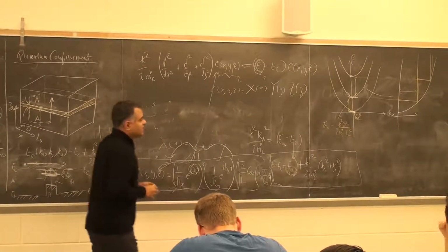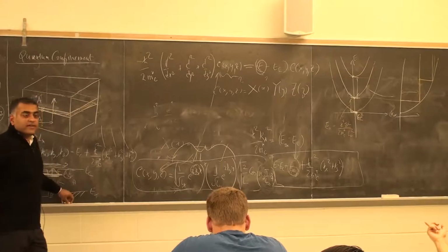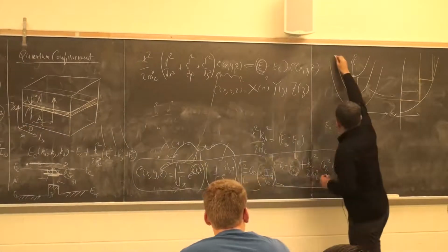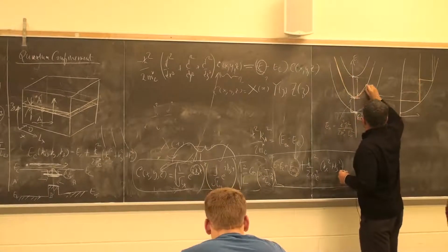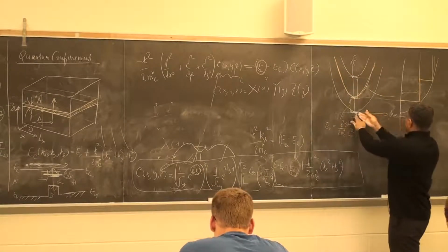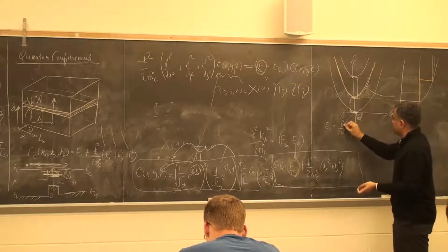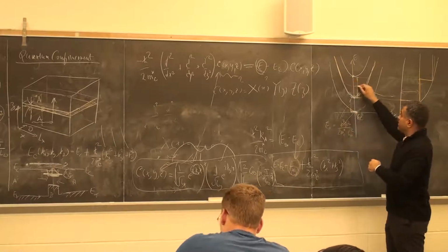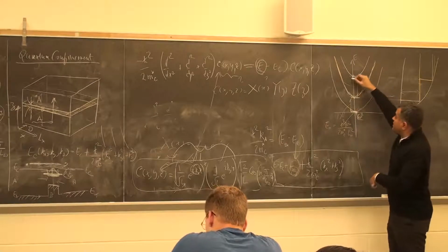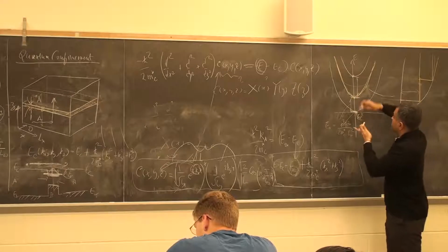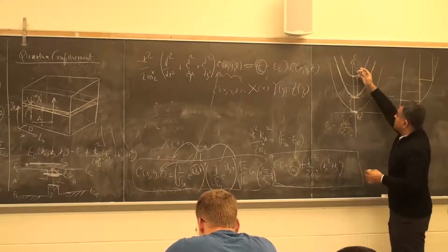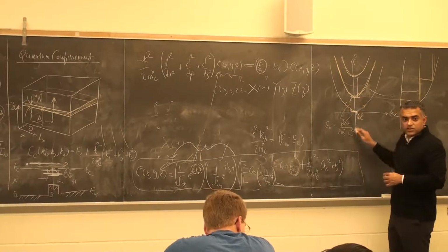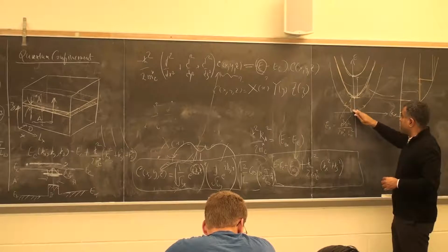Yeah, good question. So the subband is simply just the EMZ term. Correct. The subband is the name of this entire energy band. The way I'm plotting it here is only with kx, but remember in this particular example, there's also ky. So it's really a paraboloid, if you might. That's the first subband, and that's the second subband. So this energy is not allowed anymore. These energies are not allowed anymore.